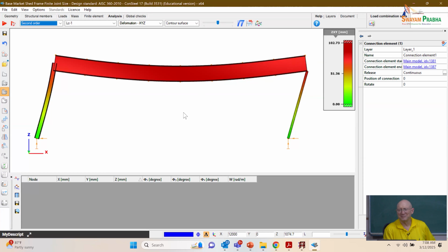We have released warping at the top, that's why. You release warping, so the in-plane displacements really aren't depending on the warping so much. So it's not that. And we had a rotational release in the model we were looking at yesterday. So it's still a rotational release.